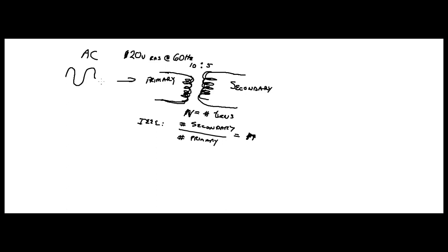So in the example above, since this is your secondary side right here, and this is your primary side over here, the turns ratio, n, would equal 5 over 10, wouldn't it? Which would be equal to what? 1/2.